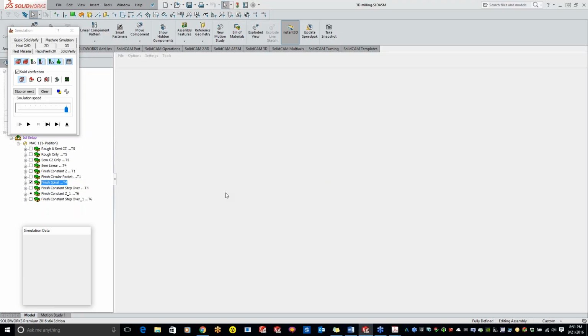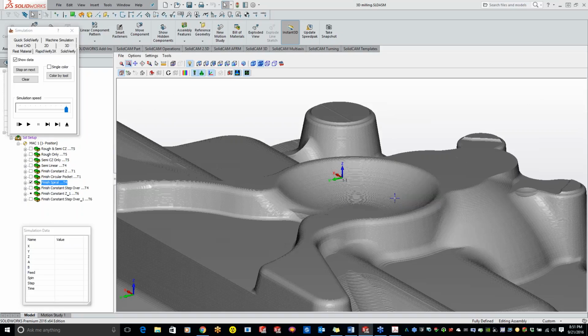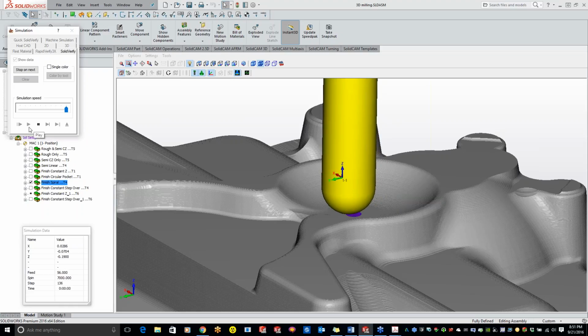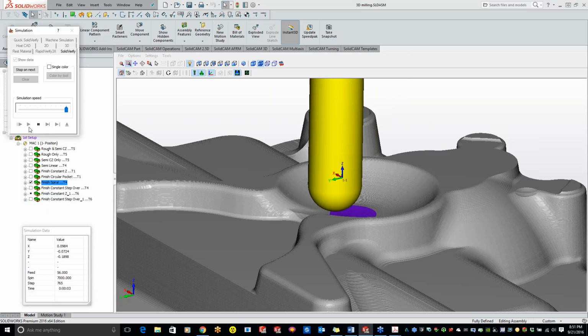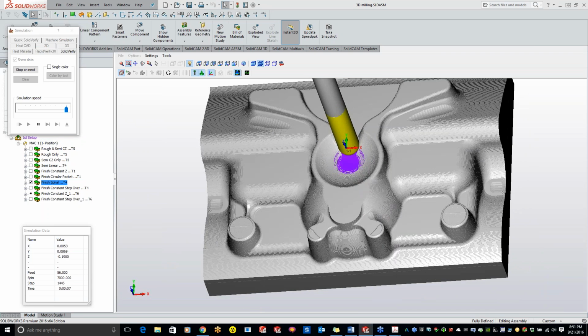Like I said, this part has been finished, but you can get a good view of what the toolpath is doing here. So we'll hit play, starting in the center, basically just a corkscrew working its way out, going right up on the surfaces. It's similar to the circular pocket, but it's just doing a perfect spiral, working its way over.